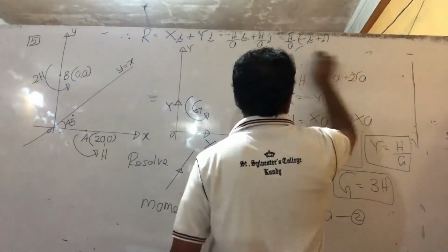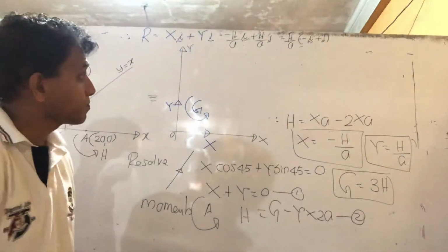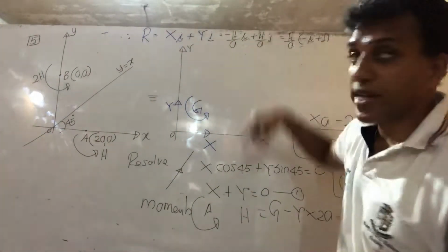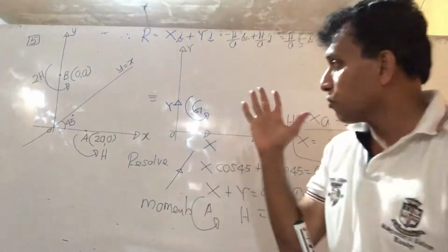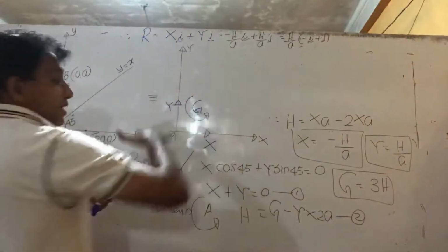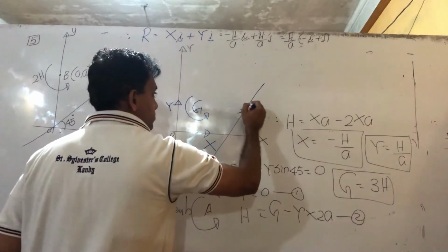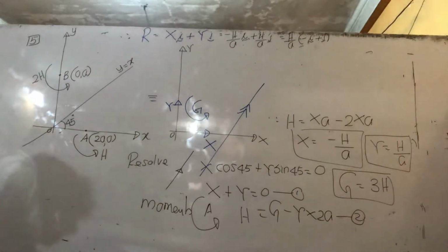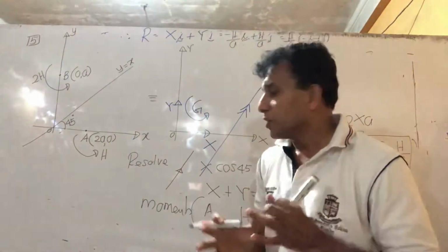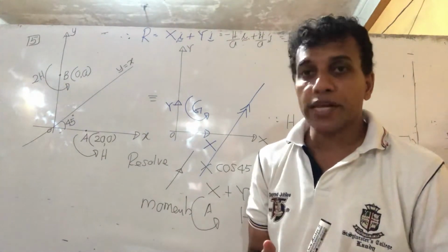And now they ask that the force acts along that direction, the line of action of the resultant's equation. So how to work that part? The resultant magnitude is okay, and the vector form, the ij component form. Now we find the line of action of the resultant. So I draw the resultant diagram reduced to a single line here. That's the resultant line. If they ask for an equation of the resultant, we should take a Cartesian pattern, the x, y component, and build up an equation, right?